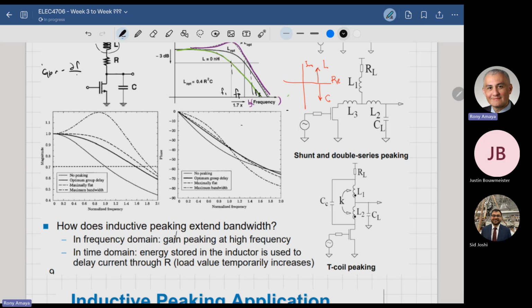And you're introducing an inductor, but what it's really doing is controlling the reactance. The reactance of an LR is hard to control, but the reactance of an LCL resembles what? A series L, shunt C, series L, shunt C, series L? A lossless transmission line. There you go.